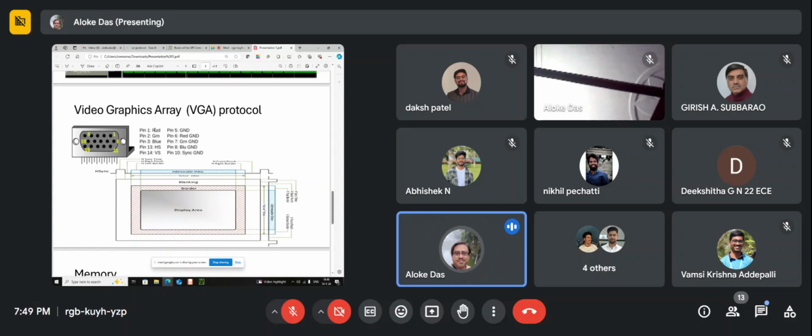First try to keep RGB fixed for all the pixels, then try to change it after a regular interval, so that you get a bar. Remember, if you have a bad screen, you get bar colors. So try to do that. Then after that, decode a JPEG picture and take the values of one JPEG picture, which will give you the RGB values of all the pixels. See if you can fit that here. Then you will see a picture really like that.